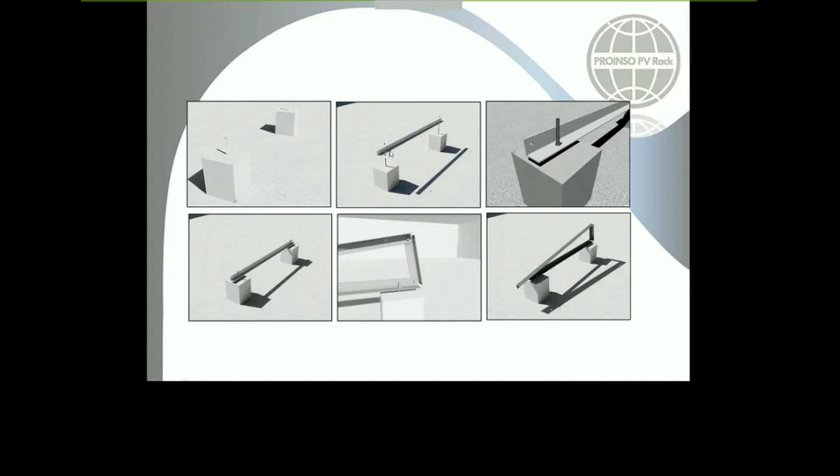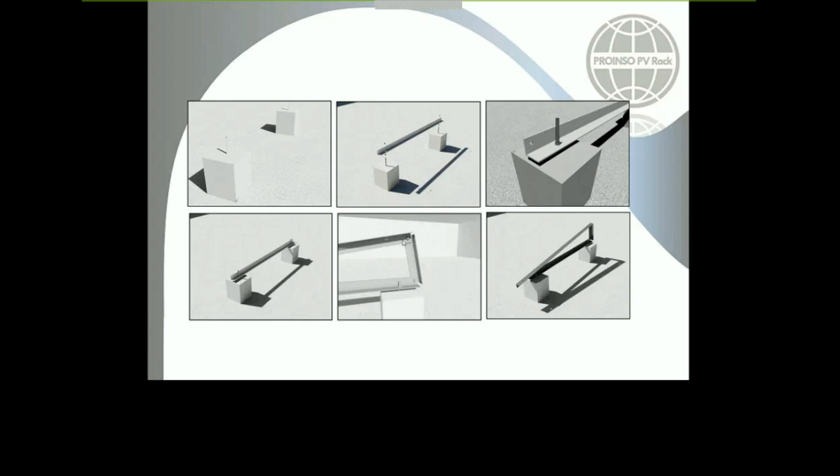When you have your concrete slabs already done, you just have to put the first piece of profile that already has the holes prepared for this, place it on there and tighten the fixing. When the first profile is already installed, for the next step, I always recommend putting the two at the same time, but not tightening the fastener until the last moment. I mean, just place it and put the washer on a little bit, but do not tighten all the fixations.